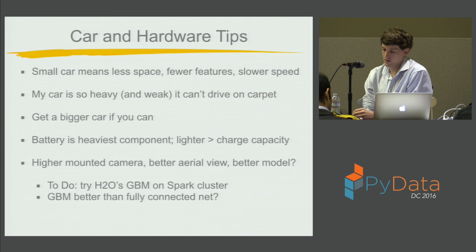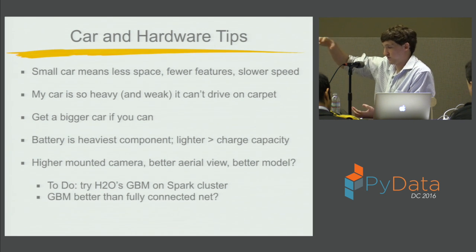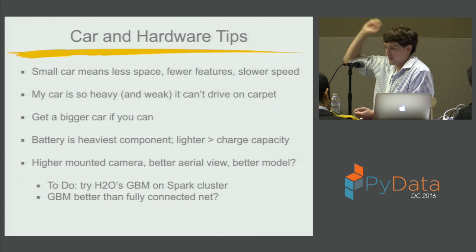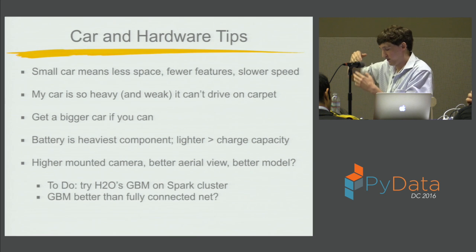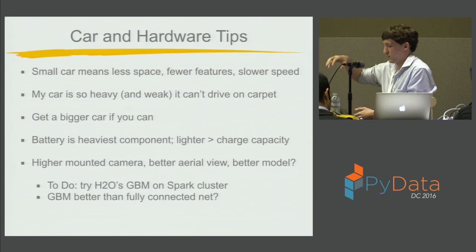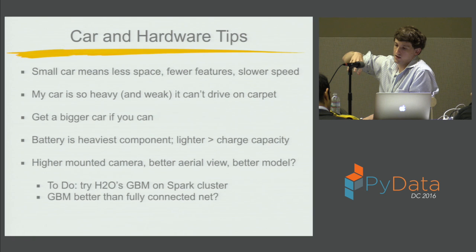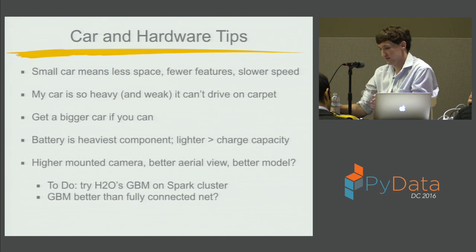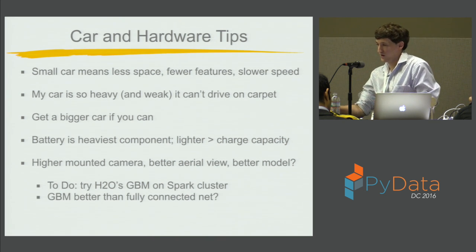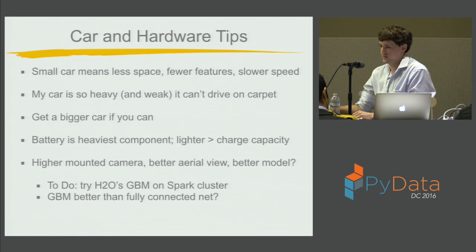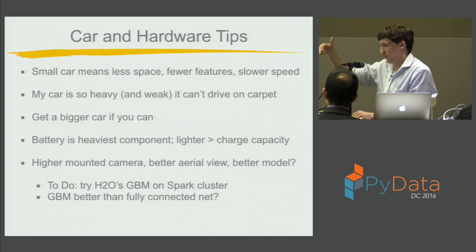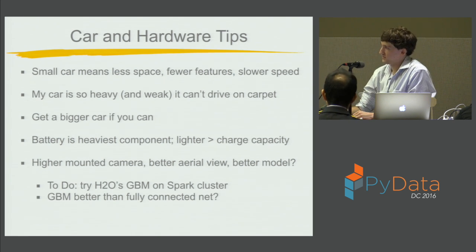Another thing I learned is that Google's actual self-driving cars have their cameras mounted really high up. You've got a really good vantage point, and you can see not only the curve that's approaching you, but also where your car is right now on the curve. I went for aesthetics over function, unfortunately, and my car has some glaring blind spots in the very beginning. So if I'm close to an edge, my car might not realize that, and it can overcorrect sometimes. If I had designed this a little better, maybe I would have had a better aerial view. So that's something to keep in mind.